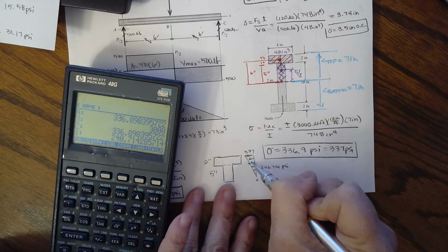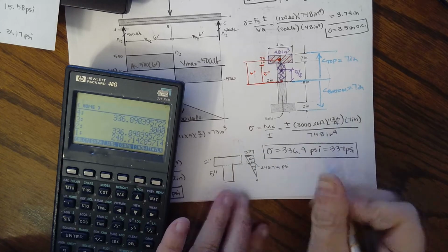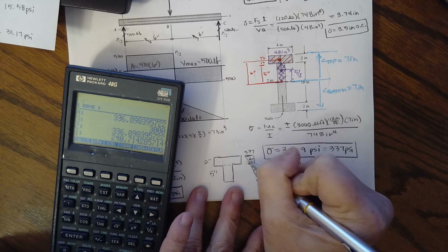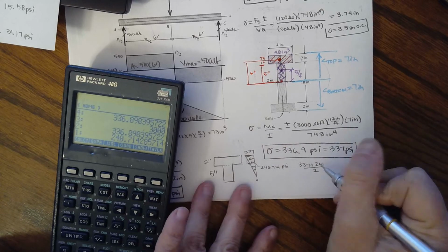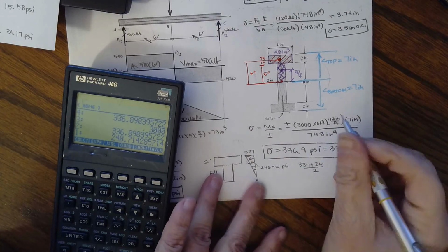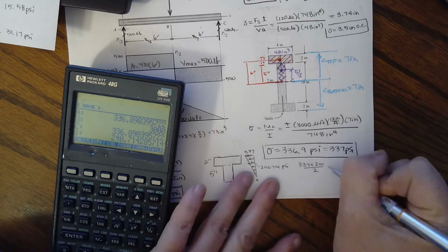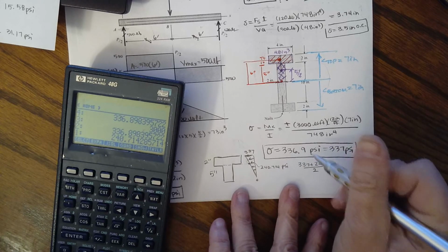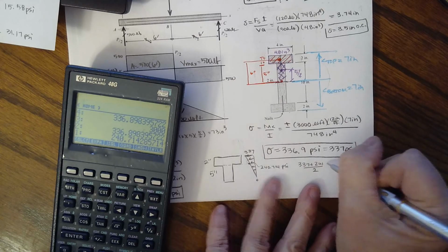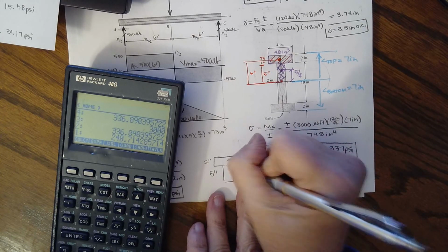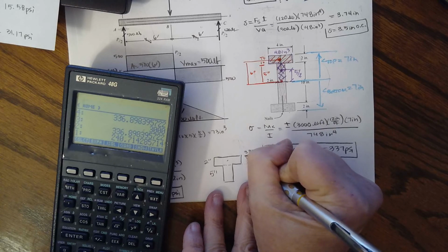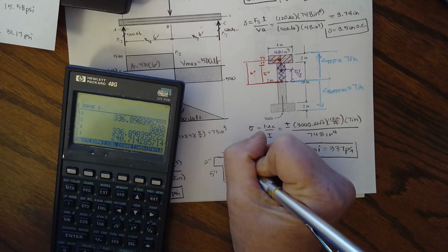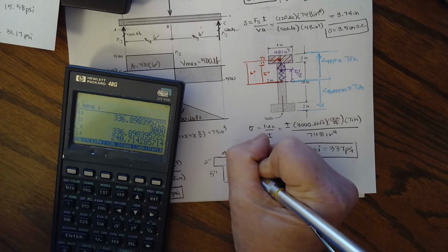And now I could find this area of stress. So I have 337 plus 241 divided by 2. That gives my midpoint, and that is psi, pounds per inch squared. Now I need to multiply by the area that it's acting over so that I can get the actual force that would come through here. These were 2 by 4 inches.